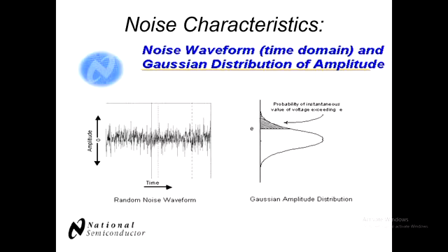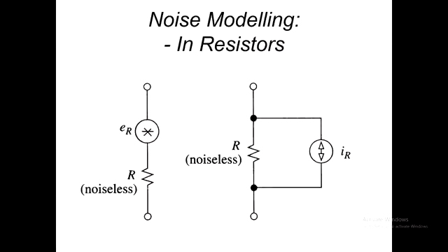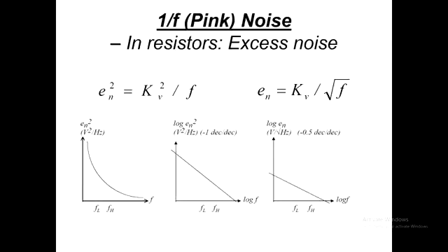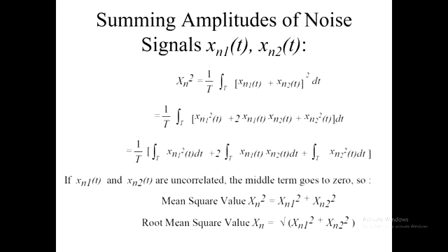Alright, now I haven't talked about amplitude distributions. Many of the noise processes we see are Gaussian, normal. What else did I need to tell you about here? Have a look at the examples in the slab of notes that I put on LMS for resistors and noise. There are worked examples in that for you to try out, to get your head around what happens in these noise scenarios.